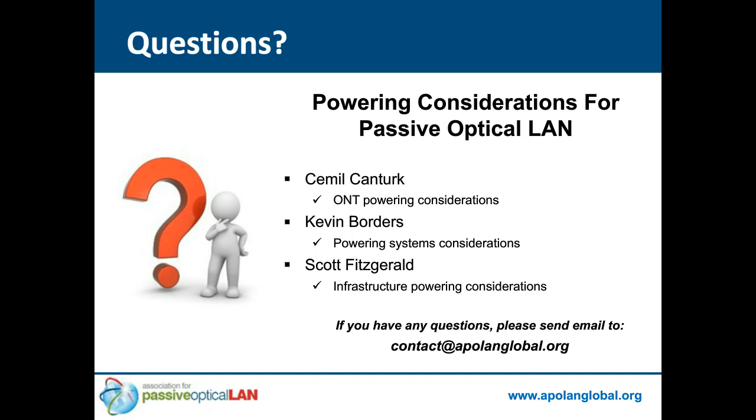The up-down DC voltage converters are used in fiber to the home, and then digital power has recently come on the market. Well, there's a couple of considerations with digital power in these applications. Basically, what digital power does is it converts the 48 volts into an elevated voltage, transports it over the cable pair or the copper wire, and then down converts it back to a voltage that's usable by the ONT, just to sort of set the stage.